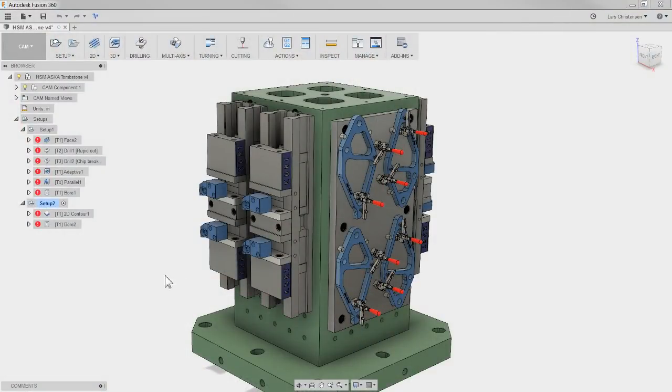So I only had one work offset, and then I worked everything from that work offset. The other option, if you have maybe multiple devices and you're switching a lot of parts around, is to actually pick up each offset on each part and have a G54, G55, and so forth. And I'm going to show you some tricks within that. So even if you're not doing any tombstone machining, hopefully you can see a couple of things that you find useful.